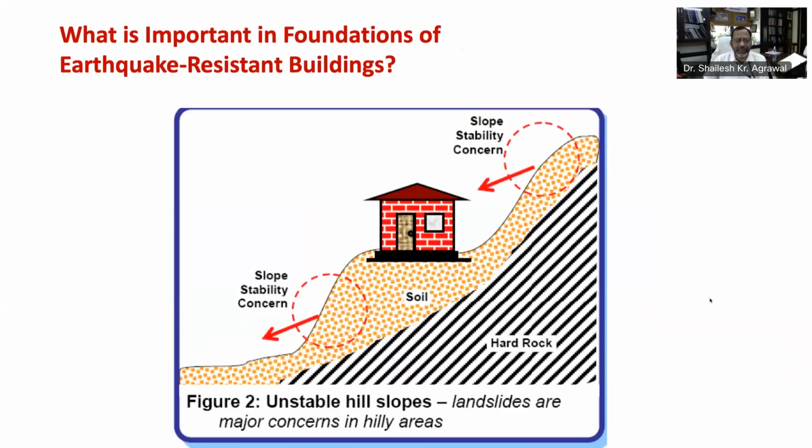Other earthquake hazards at hill slopes include rolling stones and debris. When the ground shakes underneath buildings with elongated plan or long span structures such as suspension bridge, the motion at different supports may not be synchronous. Different shaking of such structures at their support induces additional effects and should be accounted for in the design.